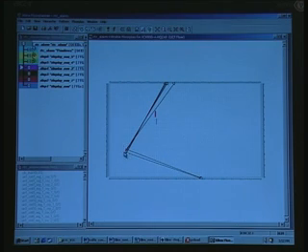For example, you can see different modules are distributed over here. The pins are connected over a long distance here, and this would naturally be an impediment to high speed of operation. So you have to relocate these pins as close as possible, so that you may enhance the speed. And this is the reason why we want to relocate both the modules as well as pins. Thank you.